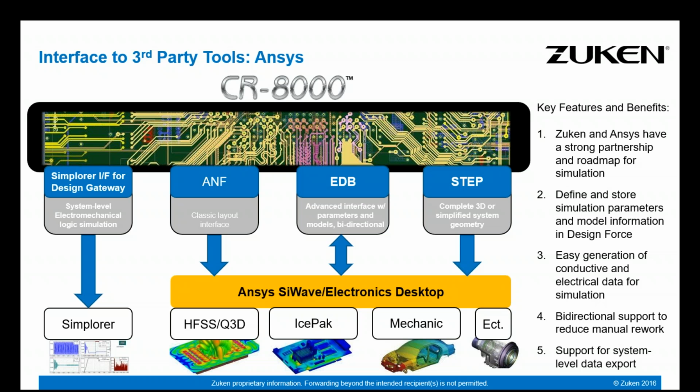It can export into ANF or EDB or STEP files so that it can be passed to different ANSYS solutions such as HFSS, IcePak, Mechanical, etc. Most of these connections are bidirectional, so that users can reduce manual rework.